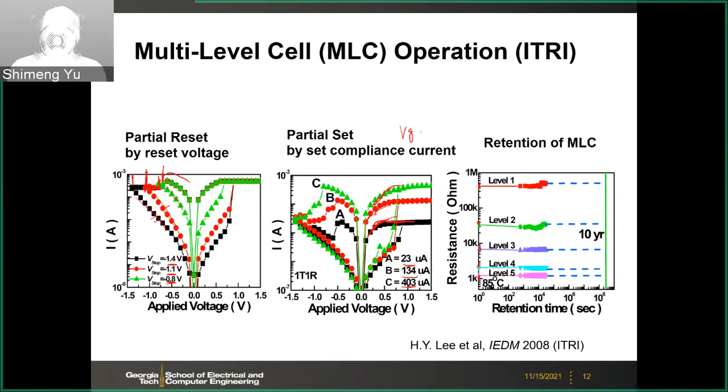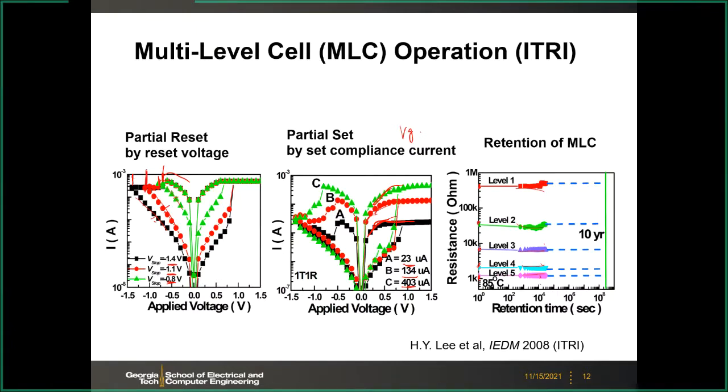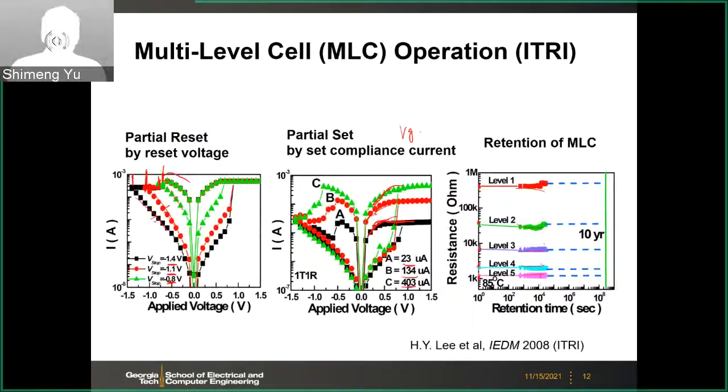And as you know, if you want to encode 2-bit data, you need 4 levels, right? If you need 3-bit data, you need 8 levels. And then you care about the retention of those multi-level states, and then you still bake that, and hopefully the multi-level states will not overlap, and then you can get reliable multi-level states. Any questions so far?